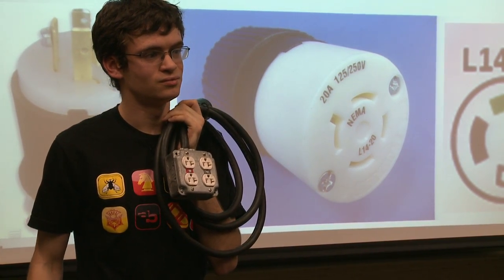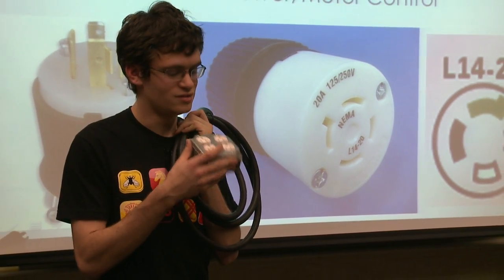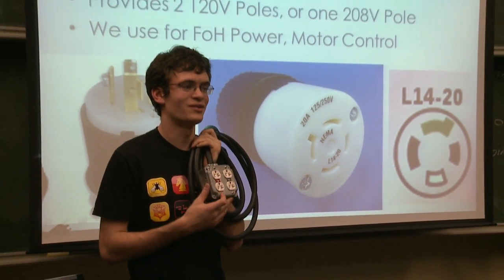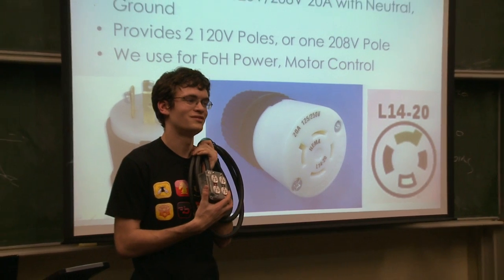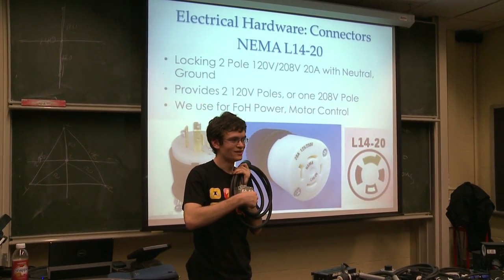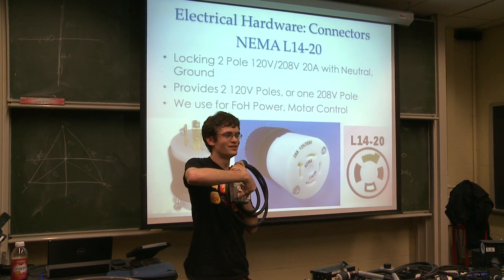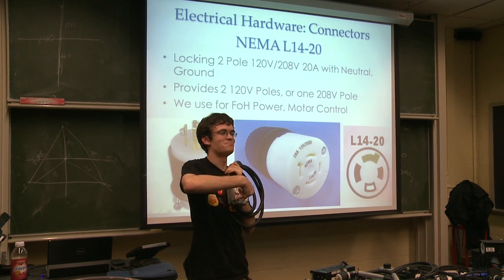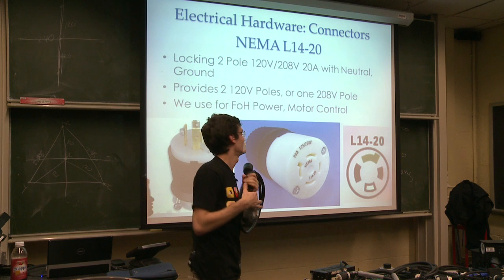Why wouldn't you get 208 volts between them? Because none of these plugs are currently wired or rated for 208 volts. You could if you plugged into here and here. That's what I mean, if you went between. Oh yeah, if you want these 2, then you could. But you really should not be doing that because you don't have a safe plug for doing that.